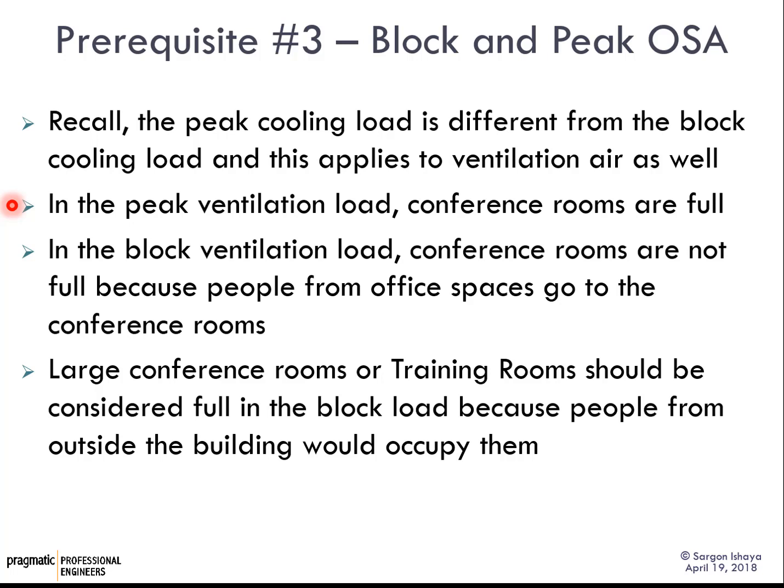In the peak scenario, the conference rooms are all full. But in the block ventilation load, we do account for the fact that, just like in the block cooling load calculation, some of the conference rooms are going to be filled by people who come in from other spaces within the offices.